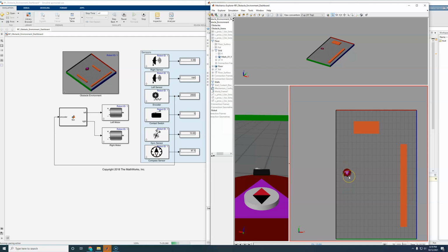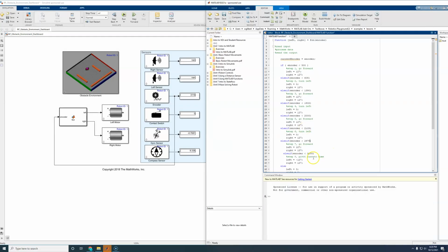So we're going to get to that center line and boop, and we're going to turn, and that's beautiful. We're going to reduce that turn just a little bit. So you see the difference between the pivot turn and the sweeping turn. The pivot turn executes a lot faster, so from 975 to 3100 is only 25 wheel ticks, but we turned 90 degrees where it was taking us 112 wheel ticks to do the sweeping left turn. So we can actually back that down just a little bit and go 30.